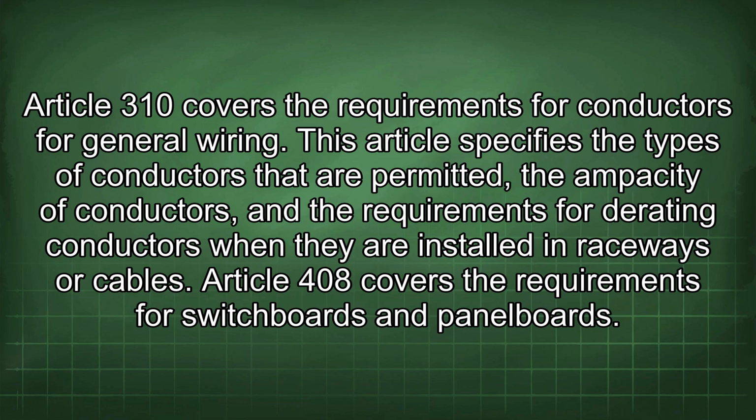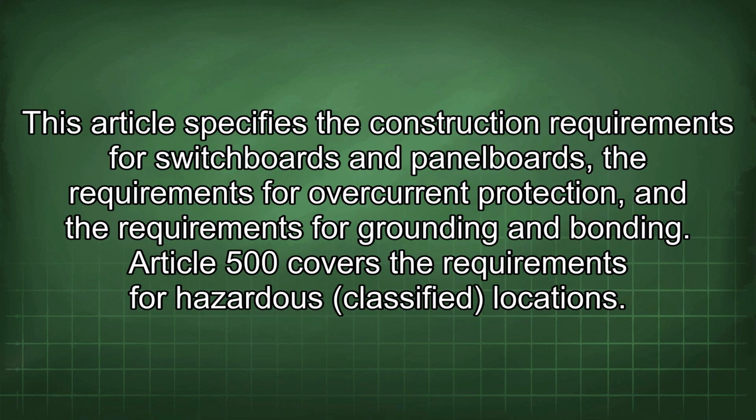Article 408 covers the requirements for switchboards and panelboards. This article specifies the construction requirements for switchboards and panelboards, the requirements for overcurrent protection, and the requirements for grounding and bonding. Article 500 covers the requirements for hazardous classified locations.